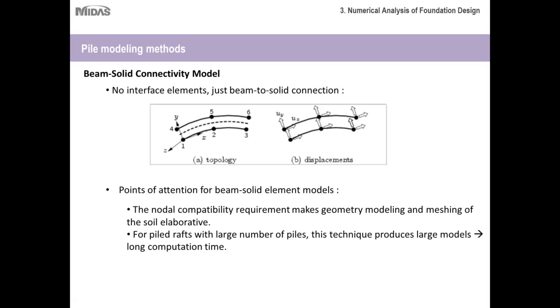is superimposed based on the stiffness of the pile and the solid strata, and therefore if this displaces by x, the pile will also displace by x. Now this is not the true behavior of pile-soil interaction. There is a relative slipping between the two, and that cannot be captured with this modeling approach. Therefore this leads to highly conservative results.